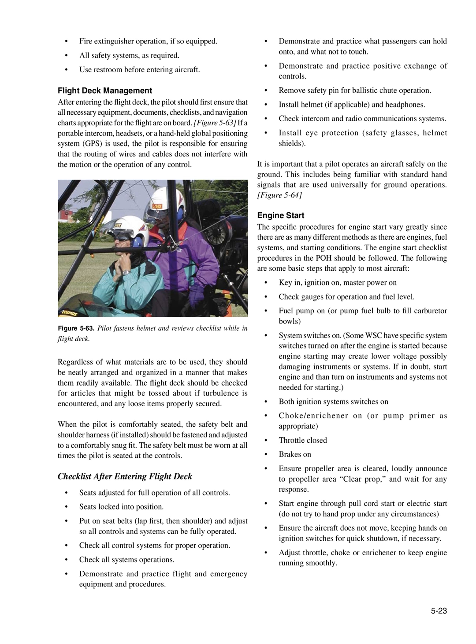Remove safety pin for ballistic chute operation. Install helmet, if applicable, and headphones. Check intercom and radio communication systems. Install eye protection, safety glasses, helmet shields. It is important that a pilot operates an aircraft safely on the ground. This includes being familiar with standard hand signals that are used universally for ground operations.